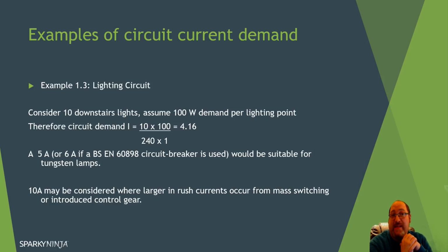If, however, that is 10 lights in 10 rooms on one switch, then no. This is the difference with demand diversity as well. You've got to consider the energizing of the equipment. If it's all at one time in the inrush, you may have to consider changing your protected device.